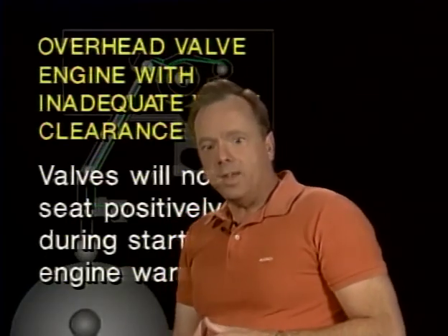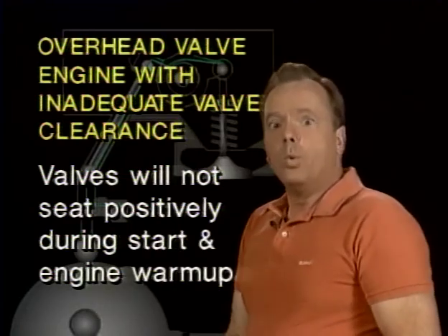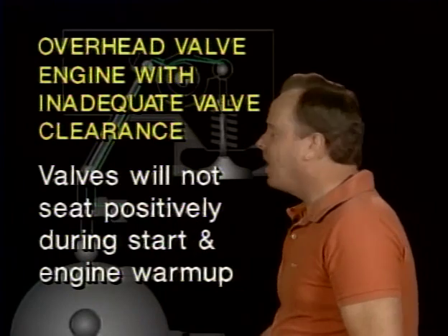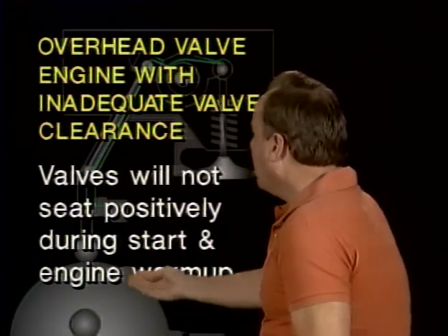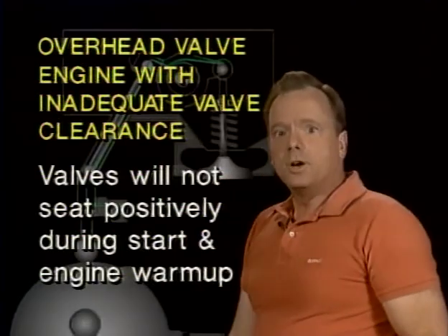Now, we've been talking about excessive valve clearance. What happens if you have inadequate valve clearance? The answer is you'll have exactly the opposite. The valves will tend to not seat positively because the valve tends to be open all the time, and during start and warm up particularly, the valves won't seat properly. So if you have inadequate valve clearance, you'd have a tendency to have the valves open too much, particularly during start and engine warm up.